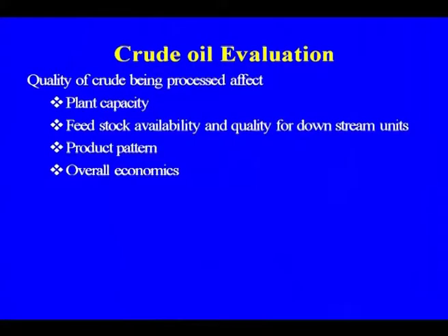So, the plant capacity, feedstock availability and the quality for downstream units, product pattern and overall economics. Because as I told you, all the refineries are now going to meet the SO2 standard for the fuel, and to meet that stringent condition definitely more hydrodesulfurization will be needed.